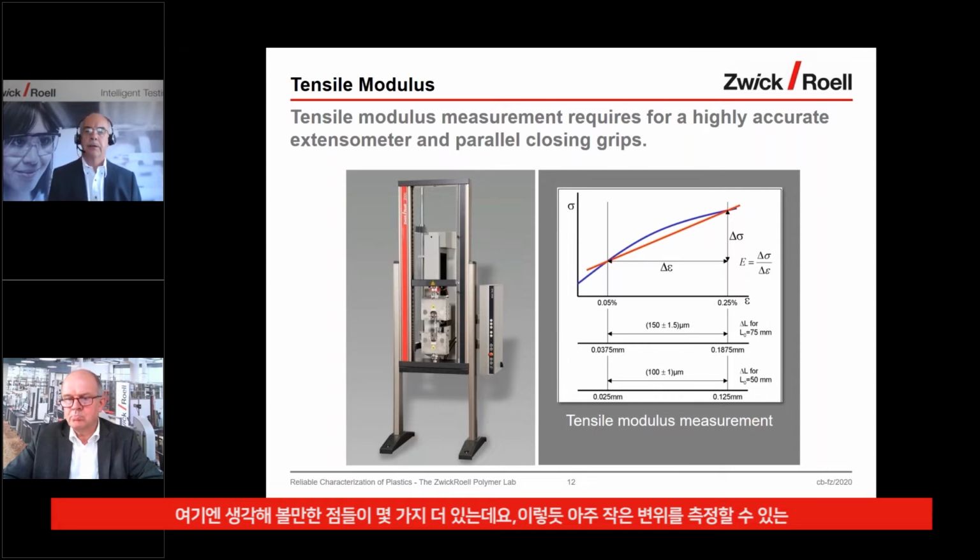I think there are more points to think about here. I think that the same extensometer that has to measure these tiny strains should also be able to measure the yield point, right? At maybe something like, let's say 30% strain, and it should also work with no loss of accuracy, even if you're using it in a temperature chamber as well. So this is not easy, right?